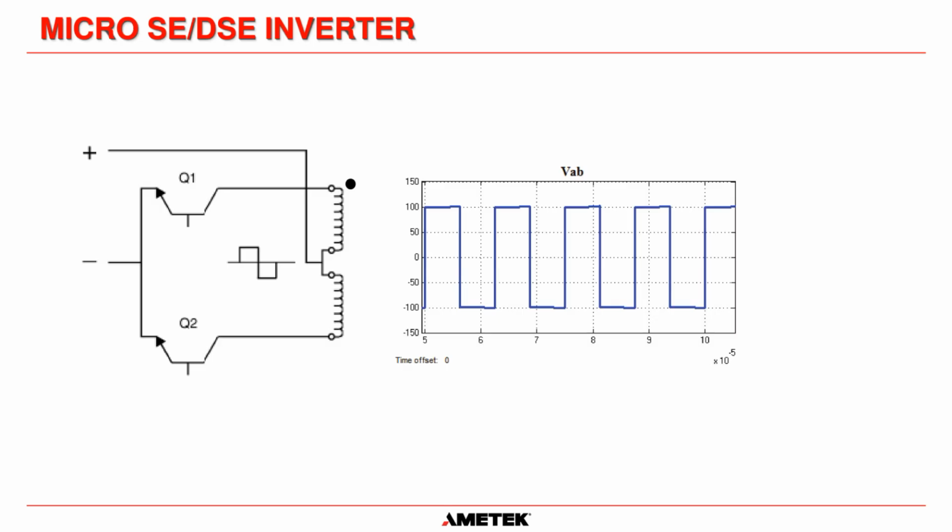And what happens is when the battery starts discharging, this voltage can go down, and this voltage here would go down. So the square wave size can actually go down. And we don't want the output of the transformer, the sine wave output, to change.